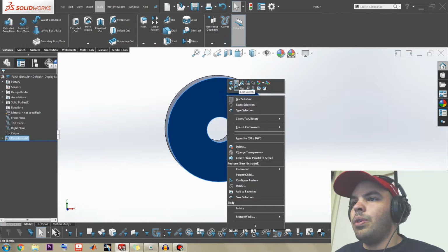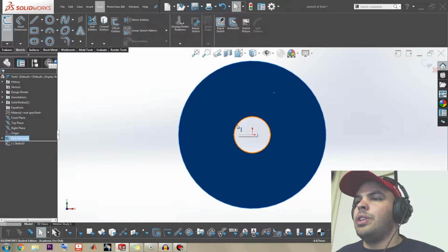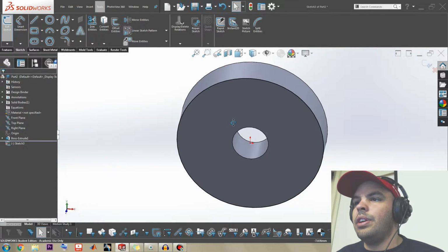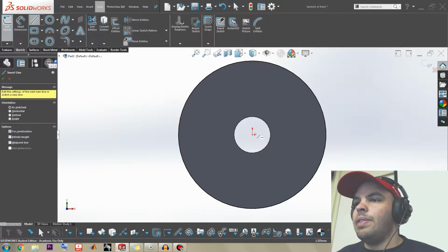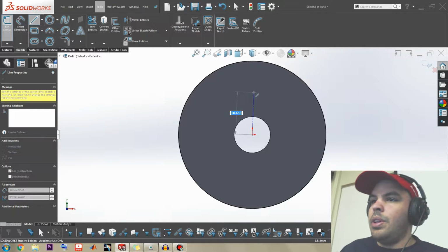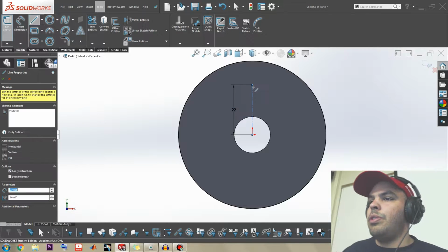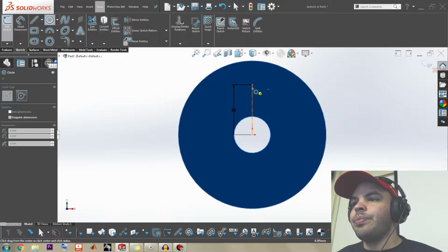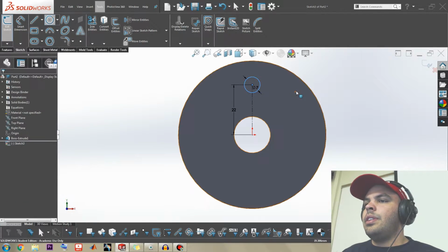And then he starts a new sketch, not edit sketch, just like that. One of the first things you want to do is convert entities, because it'll provide a relation later, and I'll tell you what that is. We'll have that center line, and we can do the same thing, align the relation up like that, 22 for the 44 millimeter bolt circle, hit escape, and bring that guy up, 7, there you go.